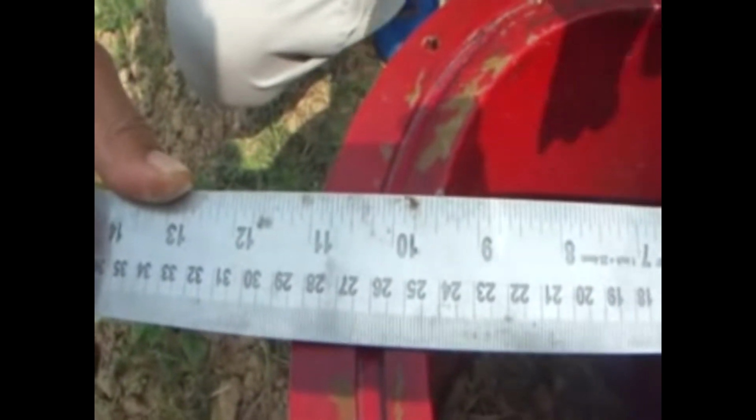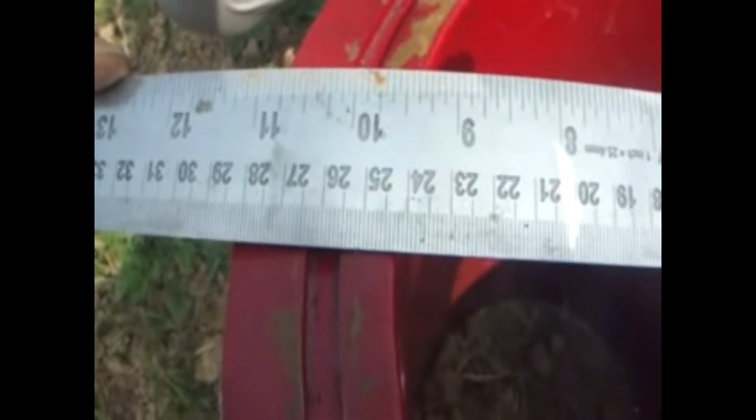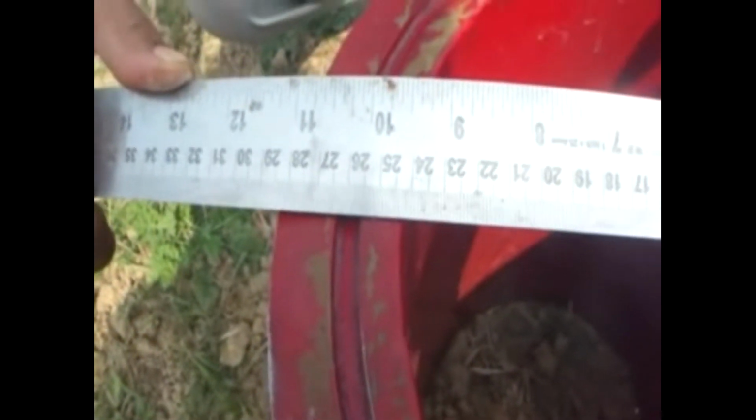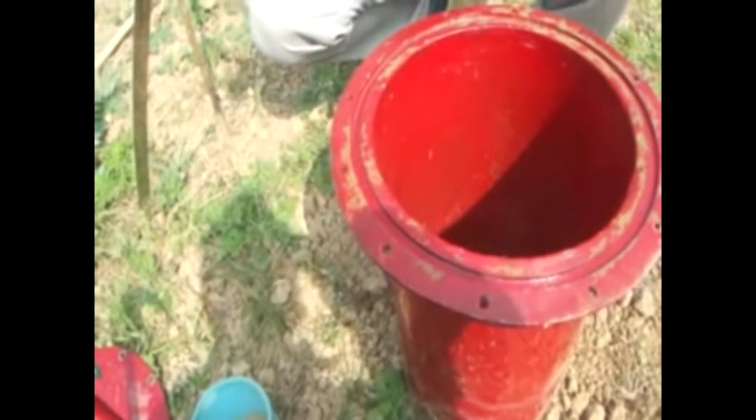So this is the cylinder. It is 24 centimeter diameter. You can see here, you can take the 24 centimeter diameter cylinder, which is inserted about 15 centimeter inside the soil. Being the quickest method, this is mostly used to find out the hydraulic conductivity of soil